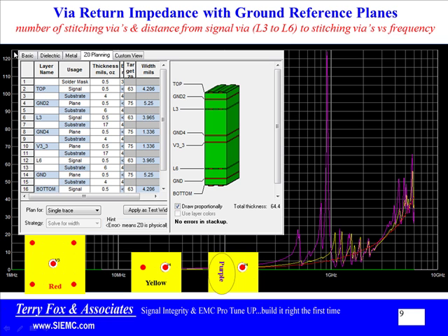So I've got an awful lot of stuff on the page at one time. The background here is impedance, so this is impedance in ohms, and on this scale is frequency. So I'm going on a log scale here: 1 megahertz, 10 megahertz, 100 megahertz, 1 gigahertz, 10 gigahertz. And if I take this very first case, which is in purple, this is where the ground-to-ground via that ties that ground to this ground is not very close to the actual via itself.